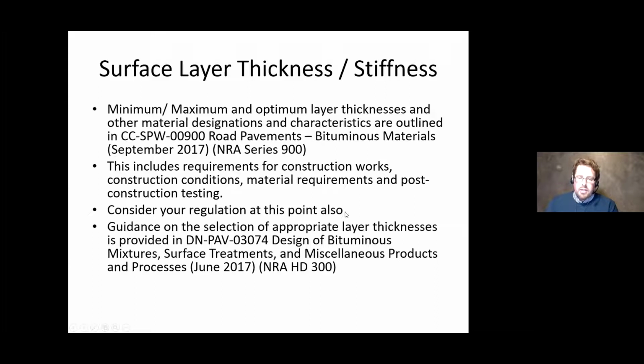Consider your regulation at this point also, that if you need to make corrections to your pavement profile using regulation, if you're doing a multi-layer replacement, can you make it up with binder layer, or will you need a regulation? And try and get your volumes correct, because the contractors will really hammer you on regulation if you get it wrong. Again, the guidance on the appropriate layer thicknesses is provided in HD 300 as well.